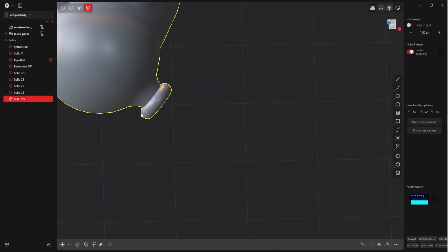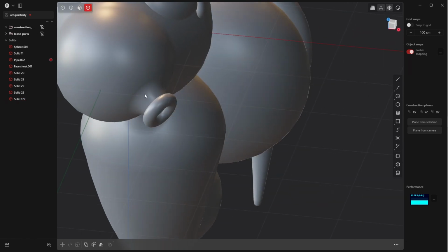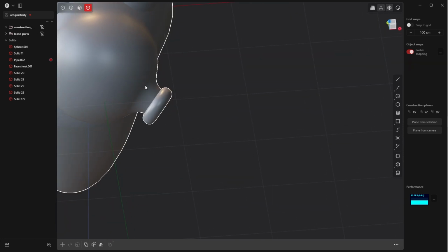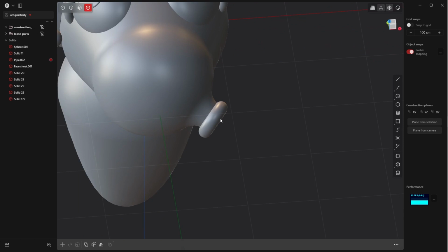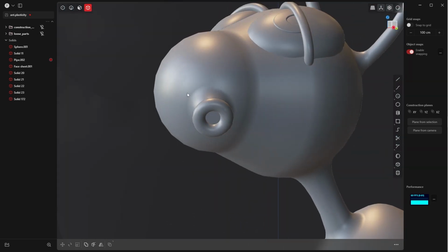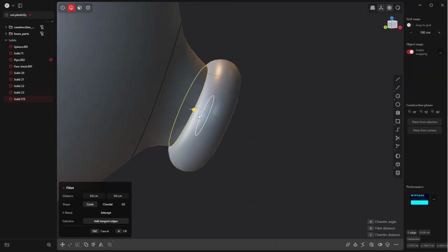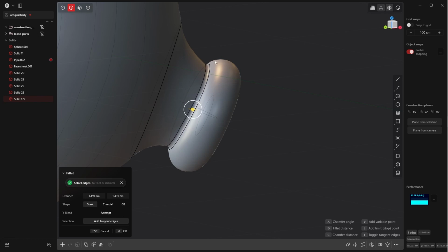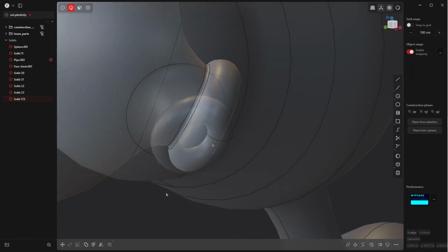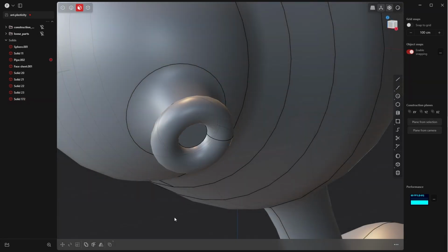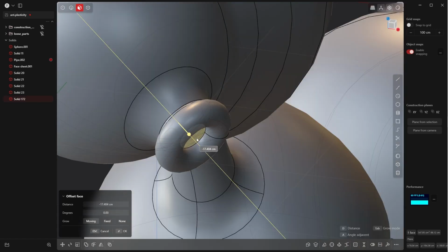Select the body. If you haven't made it already, you can join the lip, which is simply the pipe, with the whole body. Press QQ by selecting both, for making a union boolean. A slide fillet will do the job. And if we go ahead and select the face and try to move the face, we won't get that far.